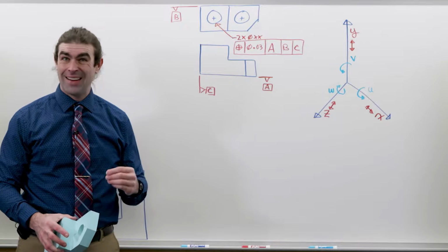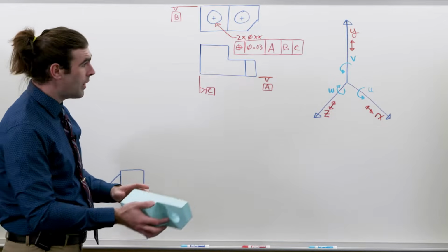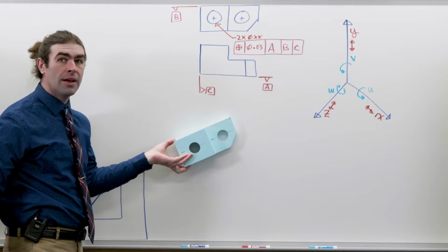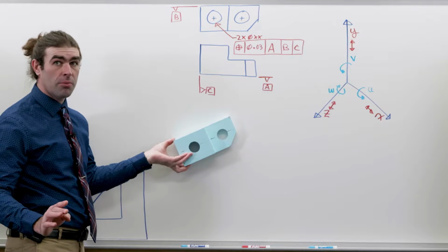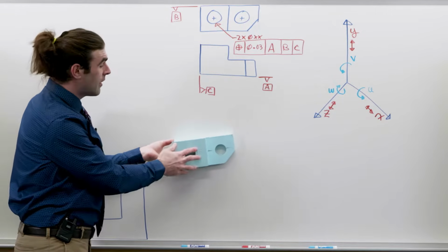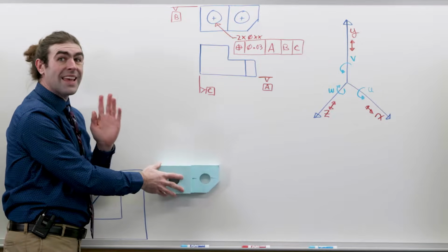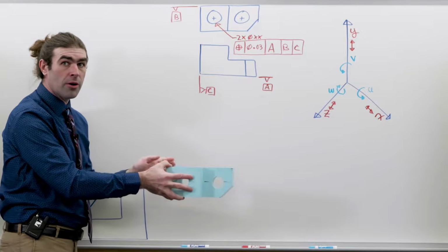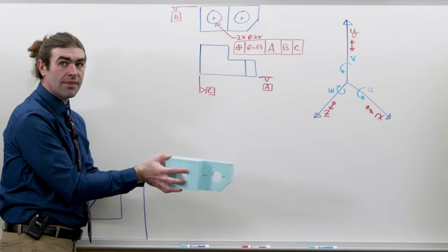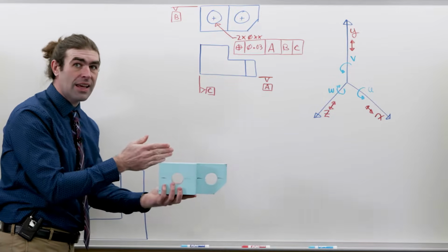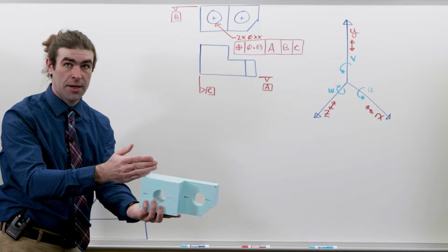order the designer intended. So if I take this surface and I put it up against my whiteboard, I've taken away degrees of freedom. Now, which ones? Well, we can move the block around, right? But we want to know where we can't move it. So if it's on the board, it can't move like this, and it cannot move like this, and it can't move in and out anymore.